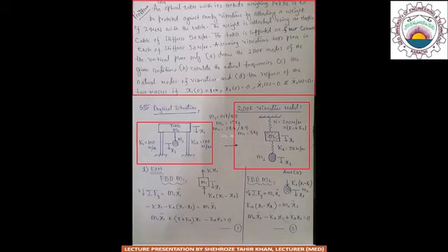The model shows the stiffness element K equal to 200 Newton per meter, which indicates the 4 elastic columns on which the optical table is supported. The mass M1 denotes the mass of the optical table, which is attached to the stiffness element K. There is another mass M2 attached to mass M1 through an elastic cable having stiffness equal to 50 Newton per meter.